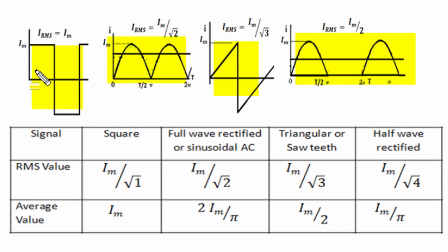So if we see a square wave, all through the positive half cycle its instantaneous magnitude always remains the same, equal to its peak magnitude or amplitude. So its average value for the positive half cycle is Im, whereas for a triangular or sawtooth wave, instantaneous magnitude linearly changes from 0 to peak value and the average value is half of the peak value. For rectified output, the average value is obtained for one cycle, and the positive half of a standard sinusoidal signal basically becomes the cycle for full wave rectified output, and for this the average value is 2 times peak value divided by pi, it is 2 Im by pi.